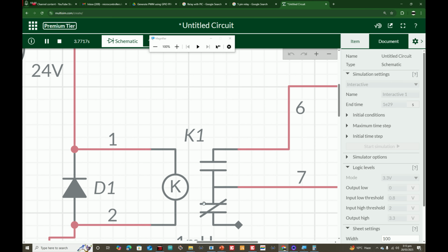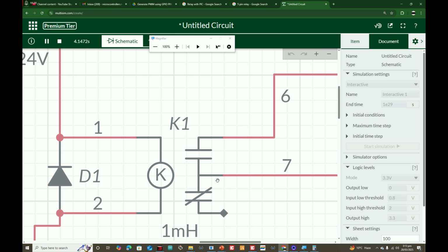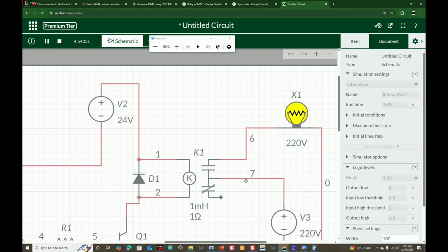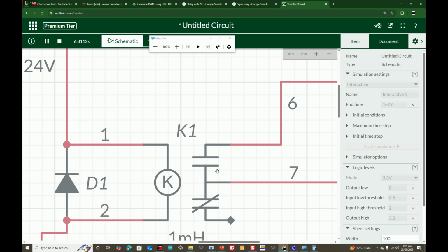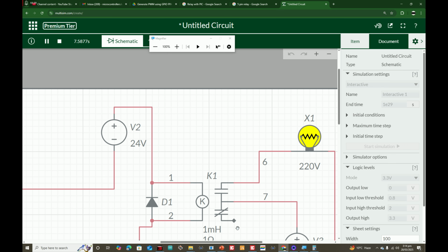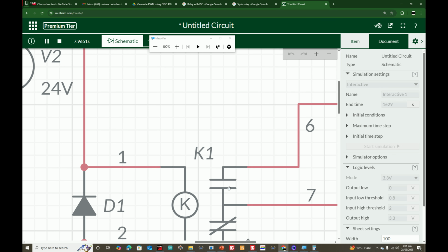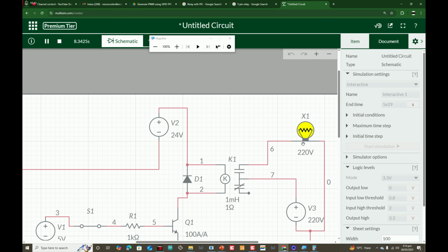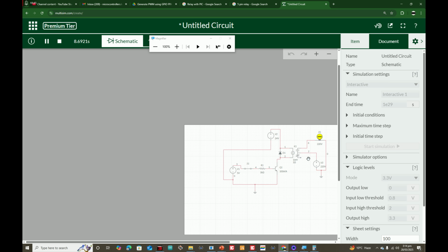So this is how this relay works. You have to power up the coil, and then you have to give common. Common can be the positive of, like, it's a series. In series you keep your circuit. Like positive, instead of going directly there, comes through the relay, either from normally closed or normally open. So we connected it with the normally open pin. So normally closed goes floating, and once the relay is triggered, this becomes closed, so the bulb turns on. So that is how it works.